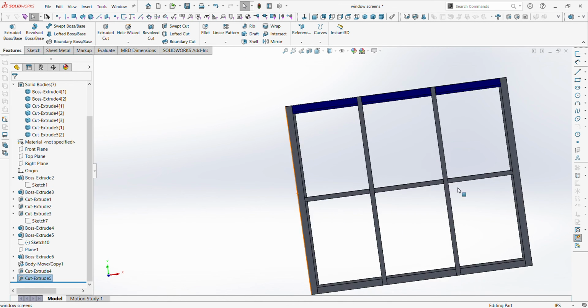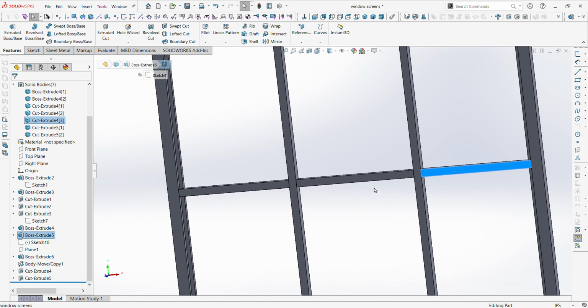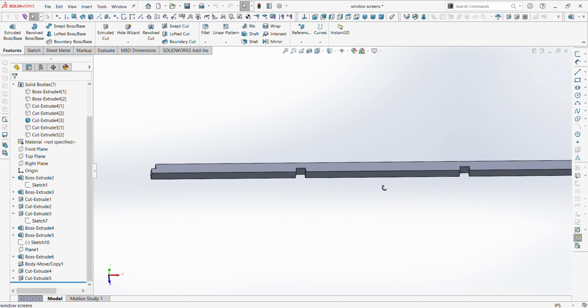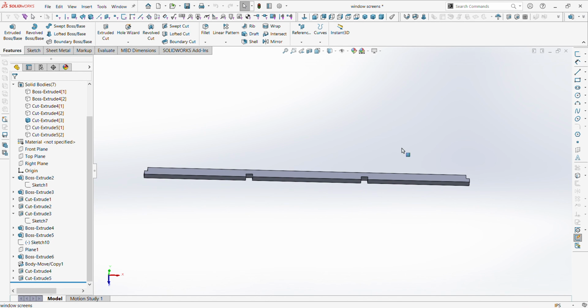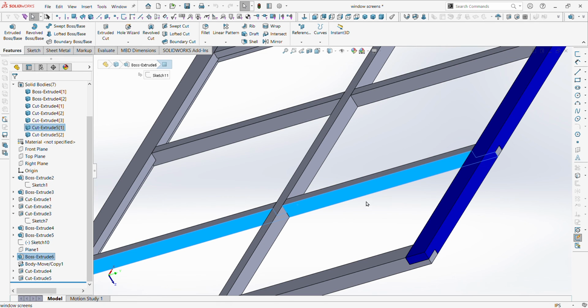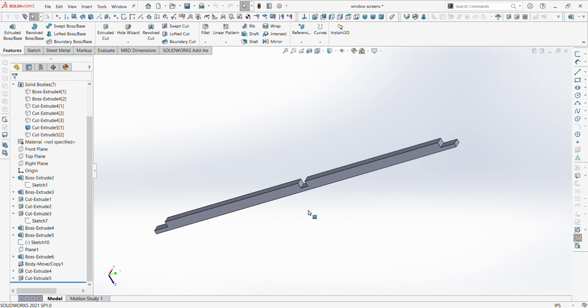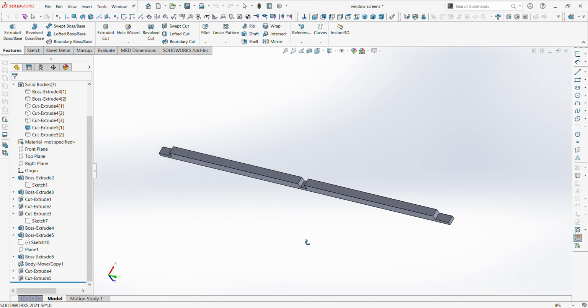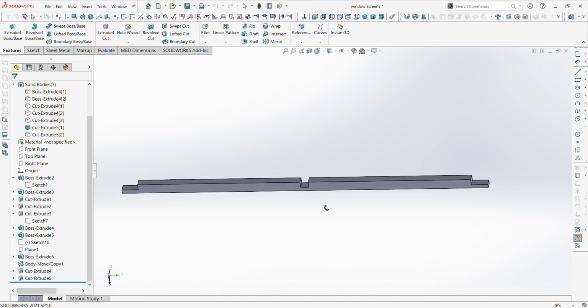Yeah, that was the right one, because it shouldn't have cut anything into more than one body, and that's what it was showing me. So, isolate. You can see now. Now this has notches. So that's how that piece will have to be shaped to be an overlap. And then this one, isolate, also has its notches. So this will all get done on the dado machine.